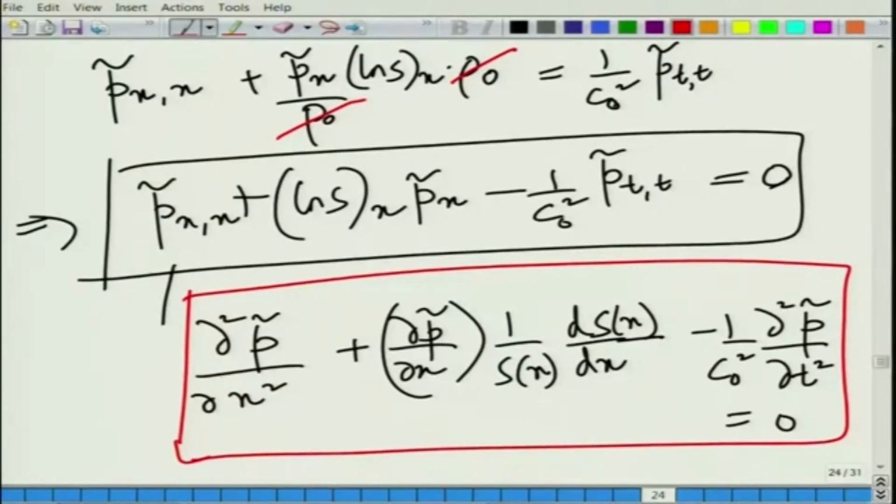Some terms I would leave to you to simplify and work out term by term, but as a check of self consistency, it is valid for plane wave propagation in a uniform duct as well if you set S x to be constant. So, this term would then go away. In general case it would not. So, we let it be, and now to derive the Helmholtz equation form for a horn.